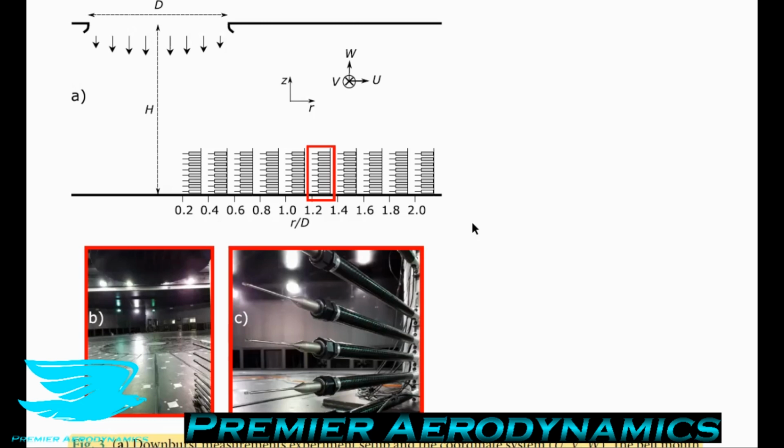Another point of view is the frequency response. If you have an unsteady flow, it means that the flow is changing in velocity with time. And all flows have this to some extent. We call this turbulence intensity level, typically speaking. However, it could just be unsteadiness in general. And if you want to measure the unsteady component, you need to have fairly big holes. The reason why is because the smaller the holes, the longer it takes for the air, and also there's damping involved, for these pressure fluctuations to make it through the tubing to the sensor. And we don't want that. We want the response to be as quick as possible. So we want to have bigger holes.